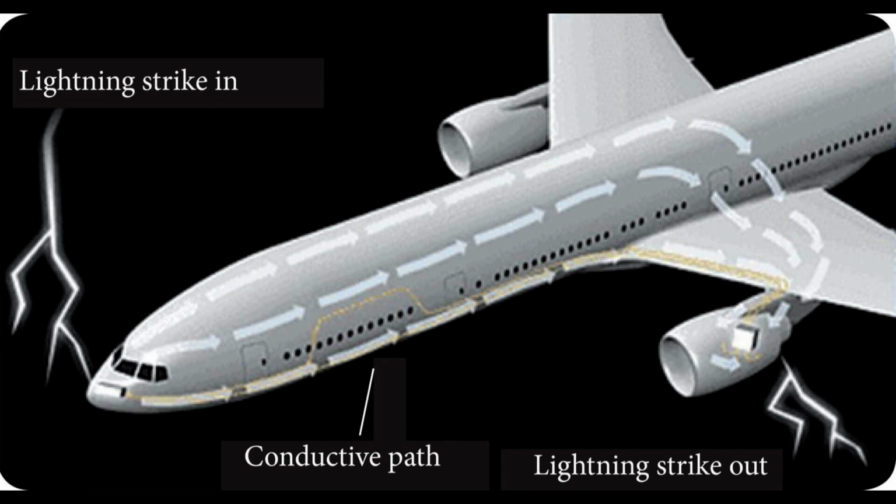For composite aircraft with internal radio antennas, there must be windows in the lightning strike mesh in the area of the antenna. Internal radio antennas may be found in fiberglass composites because fiberglass is transparent to radio frequencies, where carbon fiber is not.